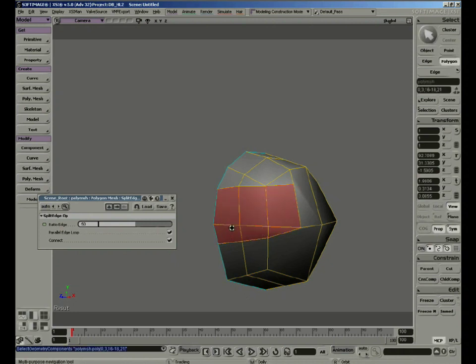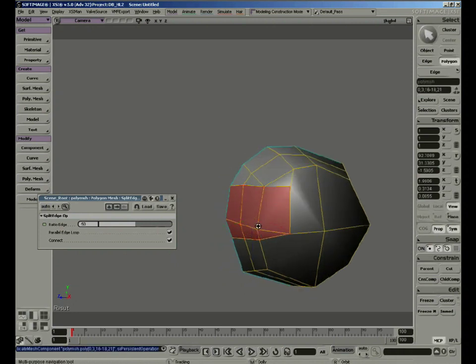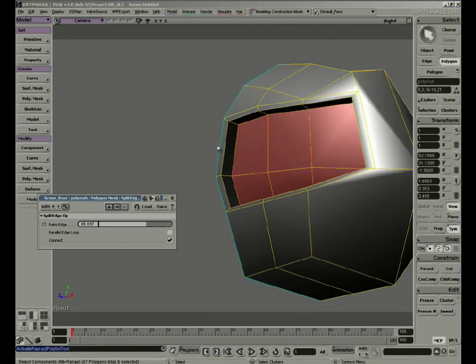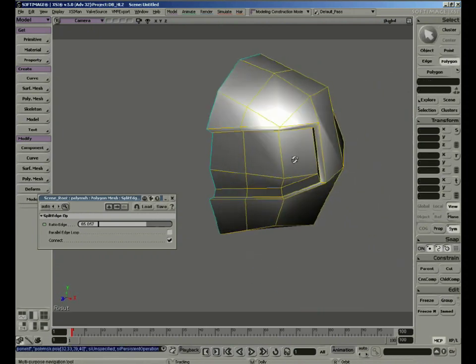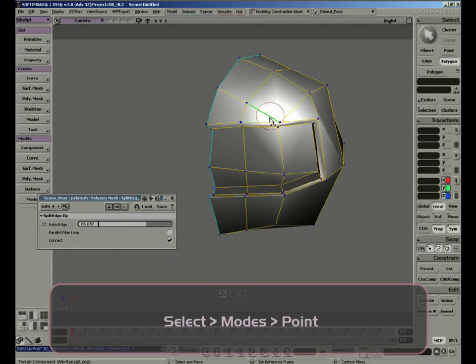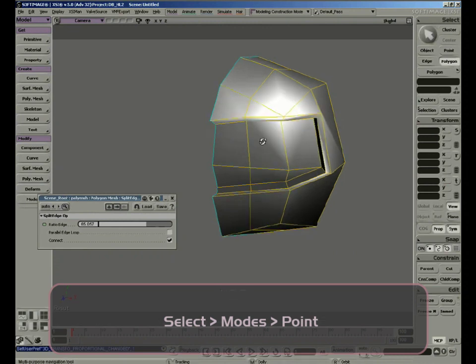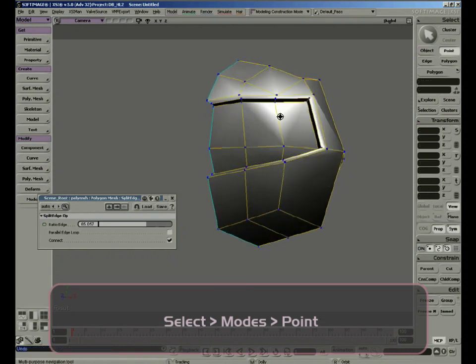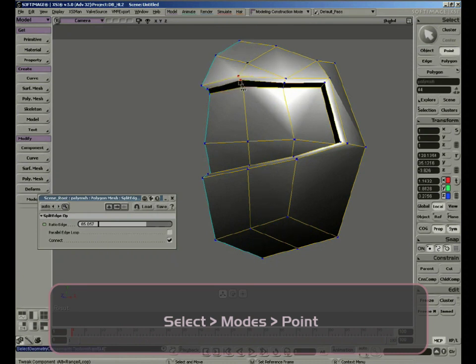In this case, I want to take these polygons, duplicate, and scale without proportional. Click and move to the inside. And now I'm going to erase these polygons right here. And using my proportional tool, so I can get a more organic slope to my helmet, I'm just going to move these up and then make some more adjustments. This one, a little bit bigger. And modify from the inside.